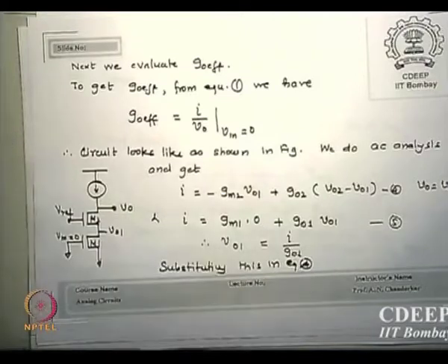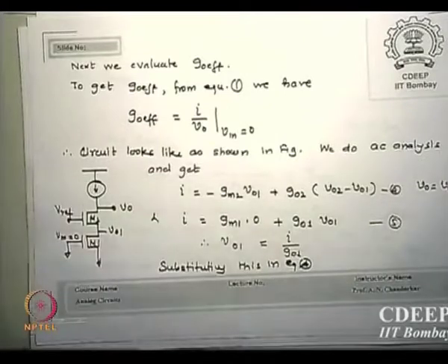M1 and M2 are biased. I am not saying VGS is biased greater than VT. Small VGS has nothing to do with bias. This is signal. The input for M2 is 0 minus VO1, which is the VGS. That is the signal it is seeing. It's an AC signal. Is that clear?